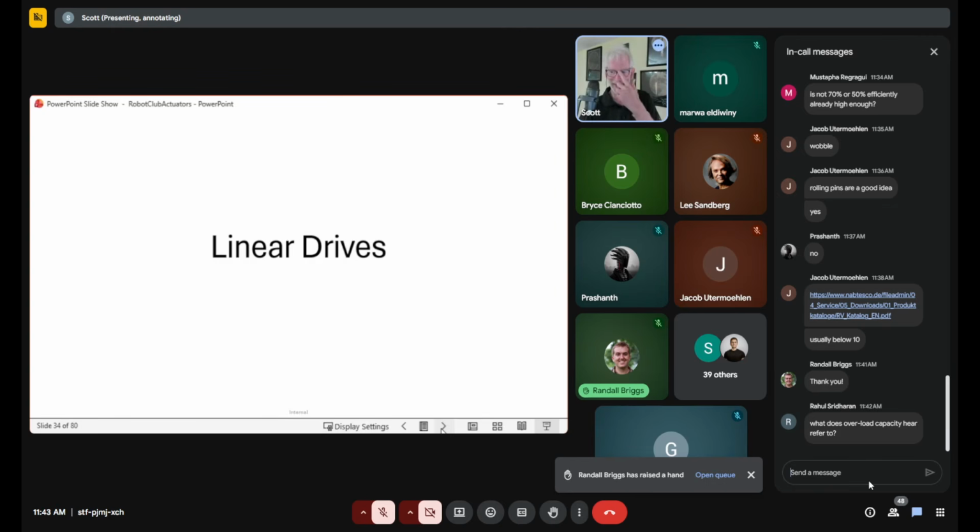I saw this video of Optimus with a jackhammer, and I wonder how long it's going to last with that, because that's a lot of vibration going right in there, and the question is whether your structure would be able to handle it. So harmonic drives may not be good for that. If you are thinking of a construction site bot, you may say, I've got to go with cycloidal or something like that. Maybe that's going to handle it better, and harmonics are not going to work.